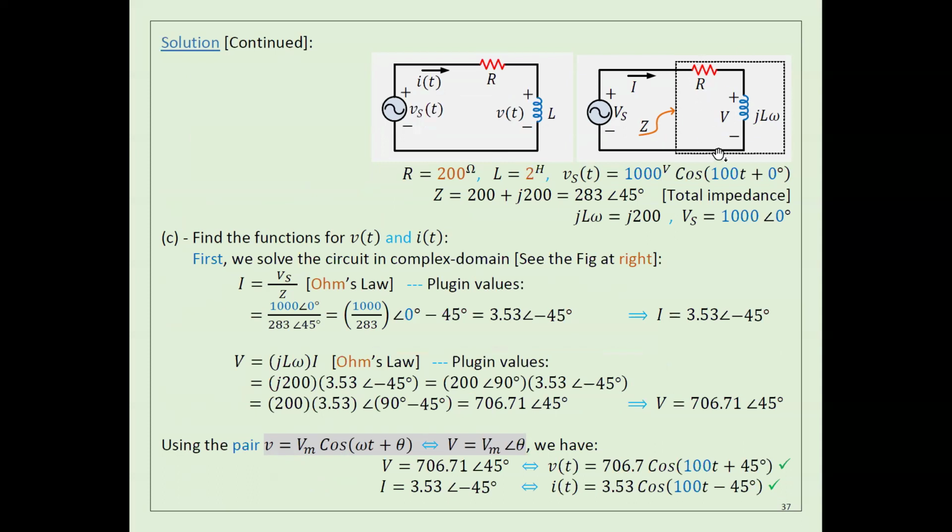Okay. I'm using the word resistance. It shouldn't be resistance, but I want you to remember what we did in the DC, right? Here is the total impedance. Okay. Anyway, so here VS, the voltage source, divided by Z. That's it. So VS here is in the complex domain divided by Z. Yeah. That's it. Once you do that, you get a current in the complex domain.